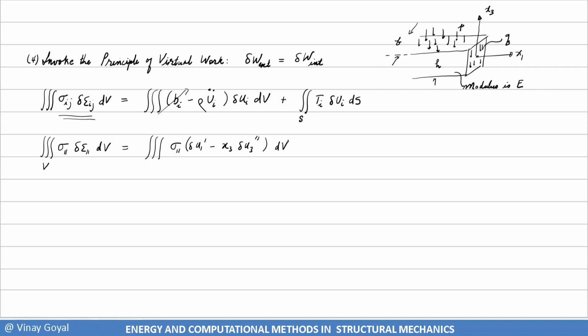And so now I'm going to try to separate these things so they're more clear. So I have this triple integral, and I'm going to write this integral from 0 to L. So the beam goes from 0 to L for simplicity. And so then I have a double integral here of sigma 1,1.